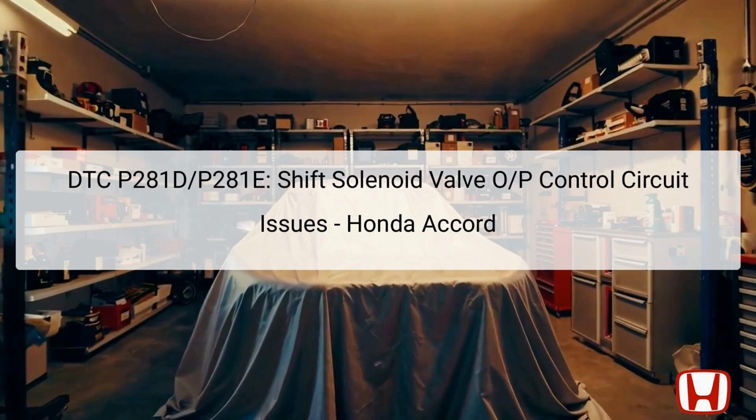The Diagnostic Trouble Codes, DTC P281D and P281E, are specific indicators that point to issues with the Shift Solenoid Valve Output, more specifically, the Pressure Control Solenoid H. These codes are generally related to the electrical control circuit rather than any mechanical faults within the vehicle's continuously variable transmission, CVT. Understanding these codes is vital for accurate diagnosis and repair.